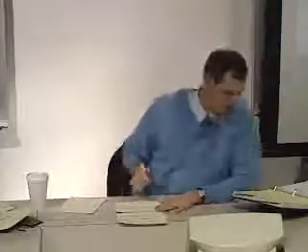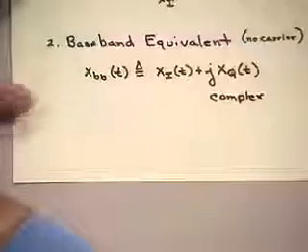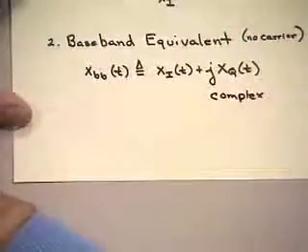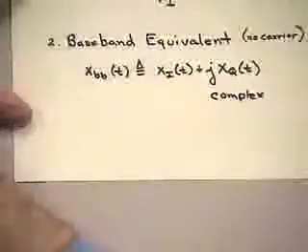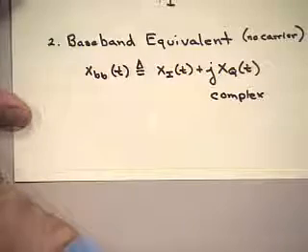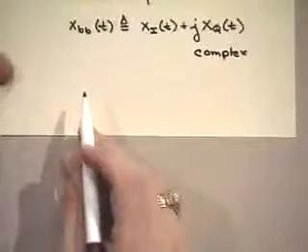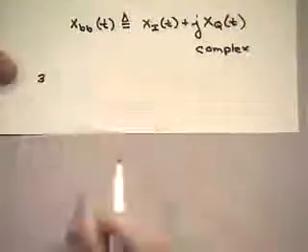So I could forget the cosine and the sine, because that's just moving it around in frequency, and look at essentially what's really going on on the cosine dimension, which is the in-phase dimension, and the quadrature dimension, which is the complex dimension. So here, in fact, I have a complex waveform that in some way represents the original waveform. Now, I do have to know the carrier frequency to actually know where it is, and what frequency band it actually occupies. But for my analysis, I'm going to try to make this independent of that. I'm going to replace that by a single complex analysis. A third yes, sir.